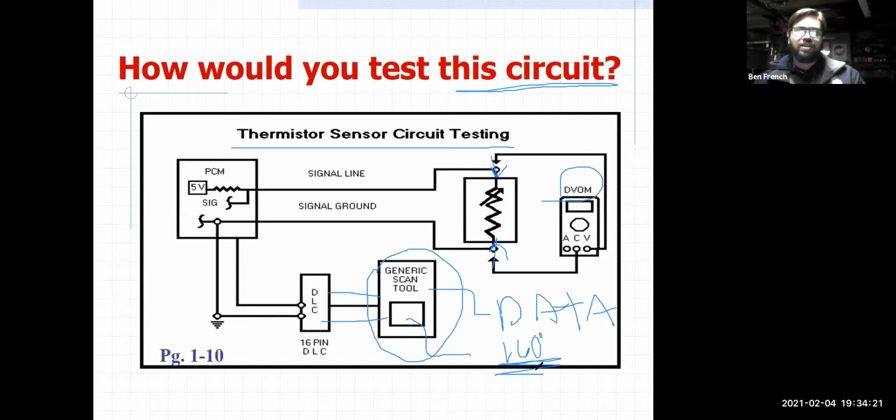So here I have a temperature probe that can work with some meters that have the temperature sensing ability. And so I could stick this in the upper radiator hose, like take the hose off, stick this in there, put the hose and clamp back on, and I can measure the temperature of the coolant and then compare that to what my meter says to what the scan tool says, right?